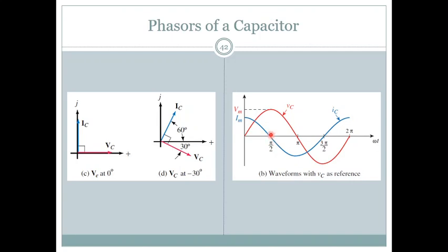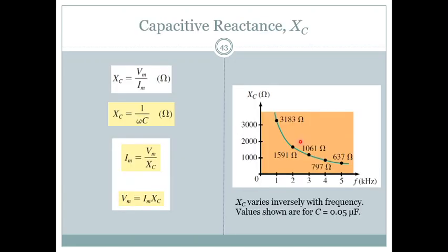This is going downwards, negative gradient crossing this point, but the negative gradient crossing for the voltage will occur exactly half a pi, or 90 degrees, after. So meaning that VC is lagging. Same for the inductor as well.